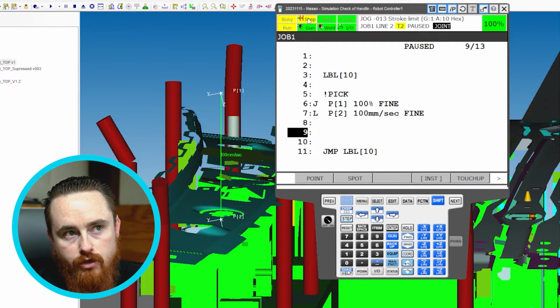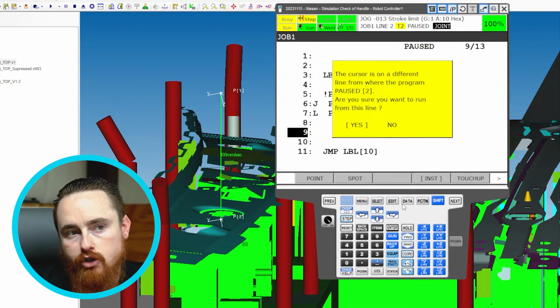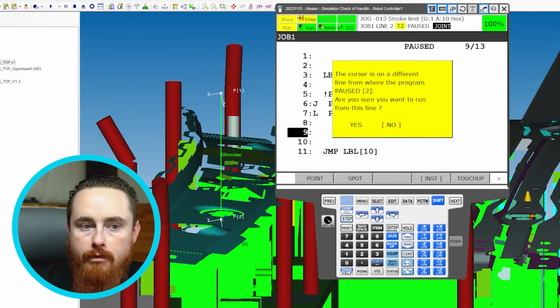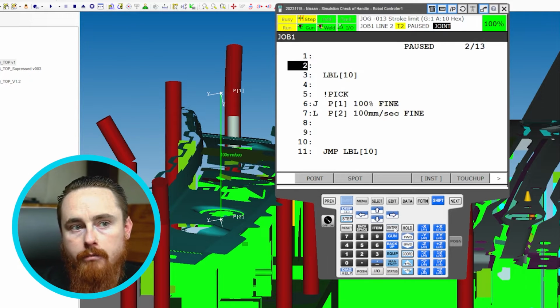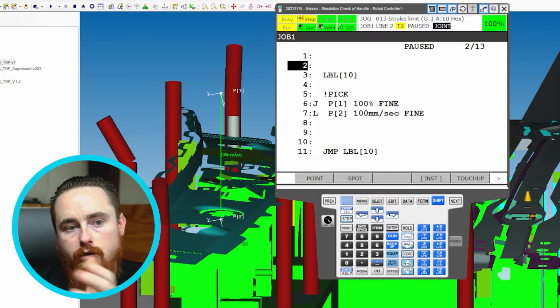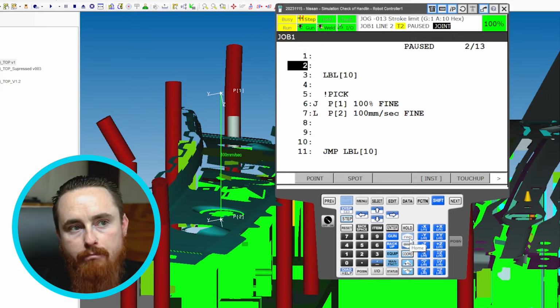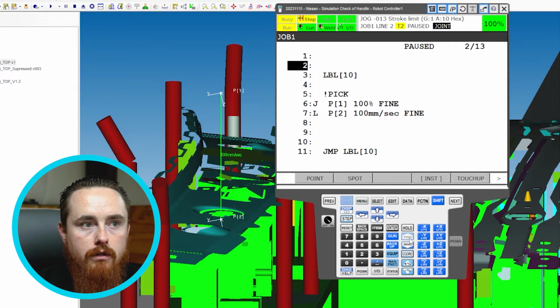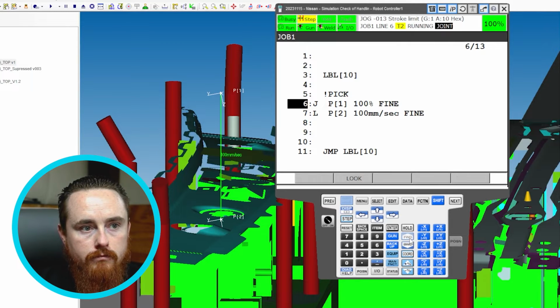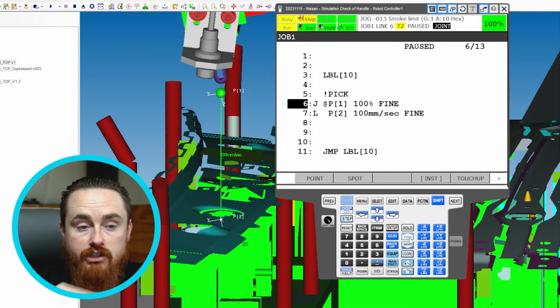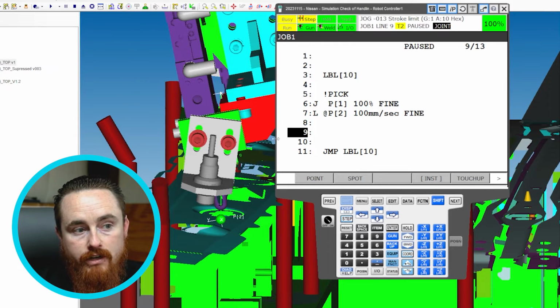Oh, we'll just do it through a brief example. So I'm in step mode, so that you guys can watch this program run. I'll say shift forward. It says, do you want to start from this line? I actually don't. I'm going to let it take me back to the top of the program. So I'll say no. It brought me to the top of the program. And I'm going to slowly step forward through this program in step mode so you can see the code execute. So here, the robot's going to move to that position. Robot's going to move to the next position.